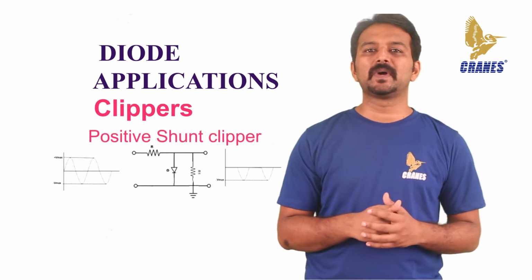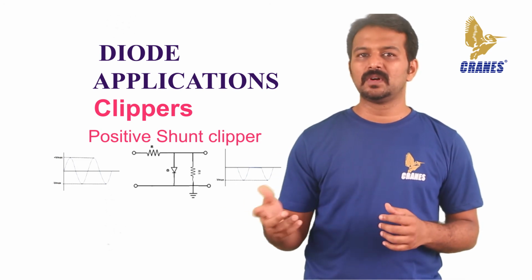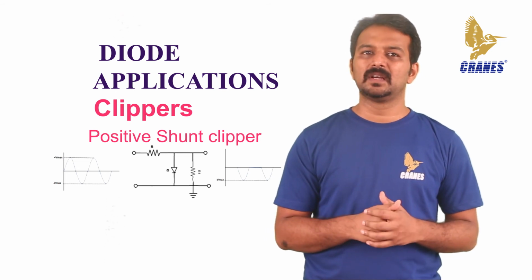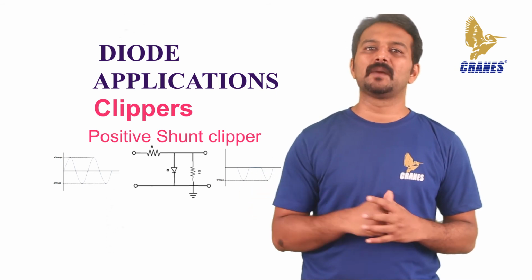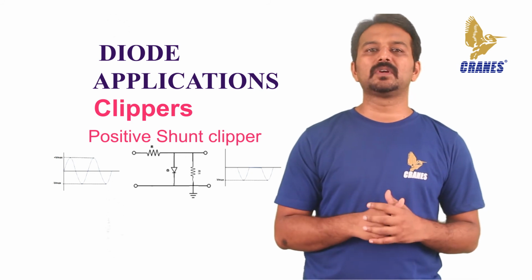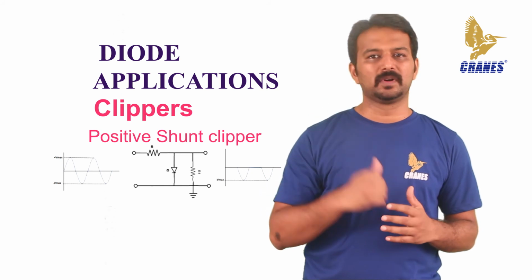Let's look at the positive shunt clipper. The diode is forward biased during the positive half cycle, so the output voltage is 0 as the diode acts as a closed switch. And during the negative half cycle, the diode is reverse biased and acts as an open switch, so the full input voltage appears across the output. With the above two diode clippers, the positive half cycle of the input is clipped at the output.